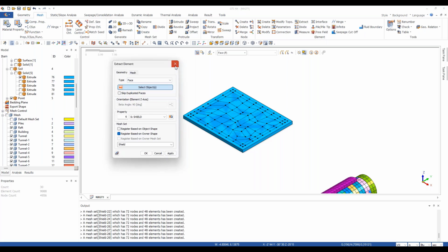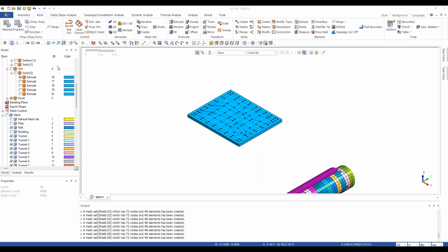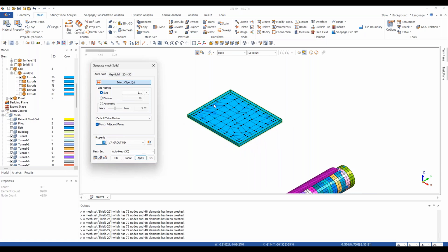Okay, what we can do is, we'll choose again 3D. In that we will choose size as 1 meter, then hybrid mesh. Since this is a topsoil but it's a cushion, I'll name it as cushion, then topsoil, because the properties of this layer would be replaced by cushion properties that are not of the topsoil, but are aggregate based properties. Okay, so topsoil,